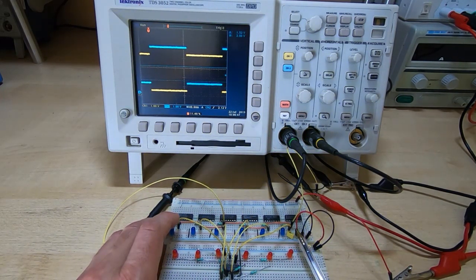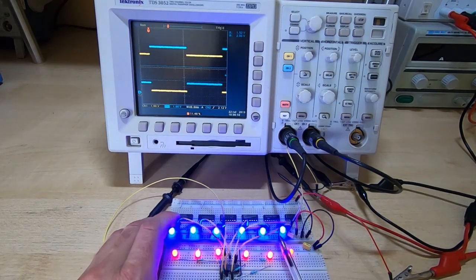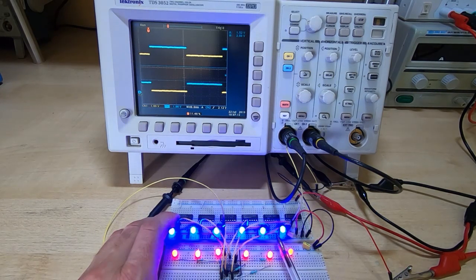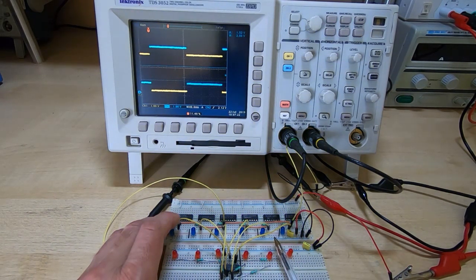HCs do have their specific uses. They have very high performance in some conditions, but you don't need it for something like the Altair. The Schmitt trigger type can have benefits if you're trying to deal with a noisy signal line, but again, bear in mind it has a much narrower window of operation with regard to input voltage levels. The output's identical to the standard LS, but the input can cause problems if you have issues with voltage swing rather than just noise.